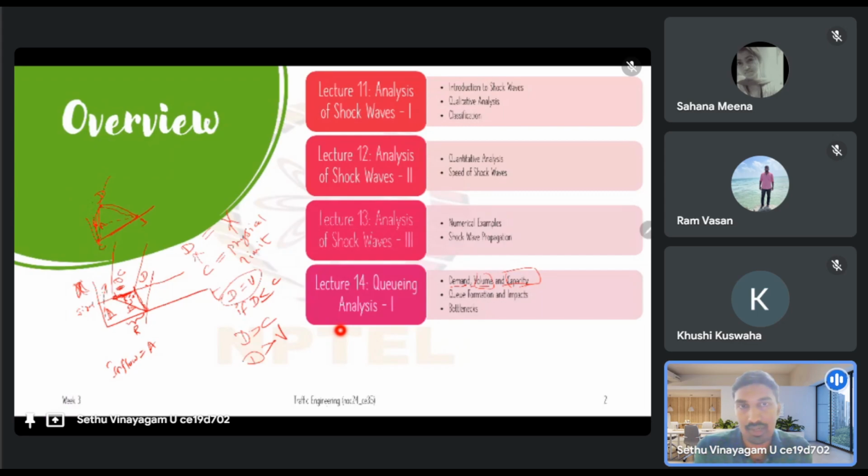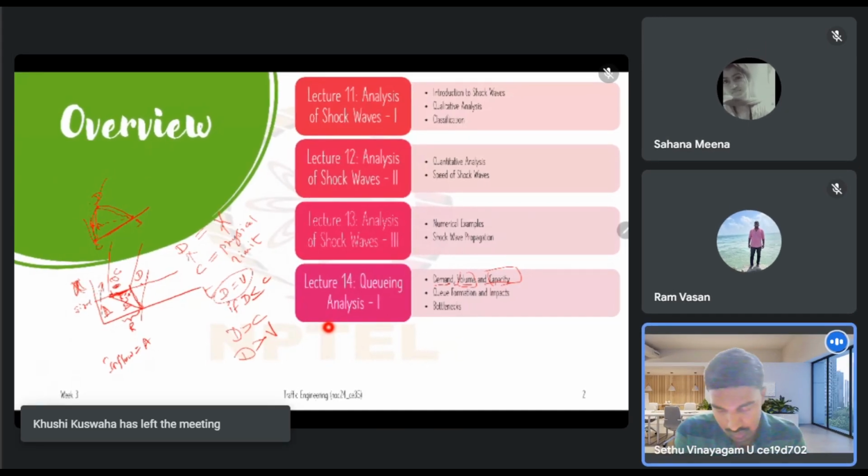They will either wait, or they can use a different route, or they can cancel the trip. We can't say what will happen to those 250; it depends on those particular drivers, right? What we can surely say is the volume will be lesser because the demand is 1,000, so 1,000 vehicles want to use, but only 750 can be accommodated, right? So volume will be lesser than the demand. That much we can say. So that's important to understand: the difference between demand and volume.